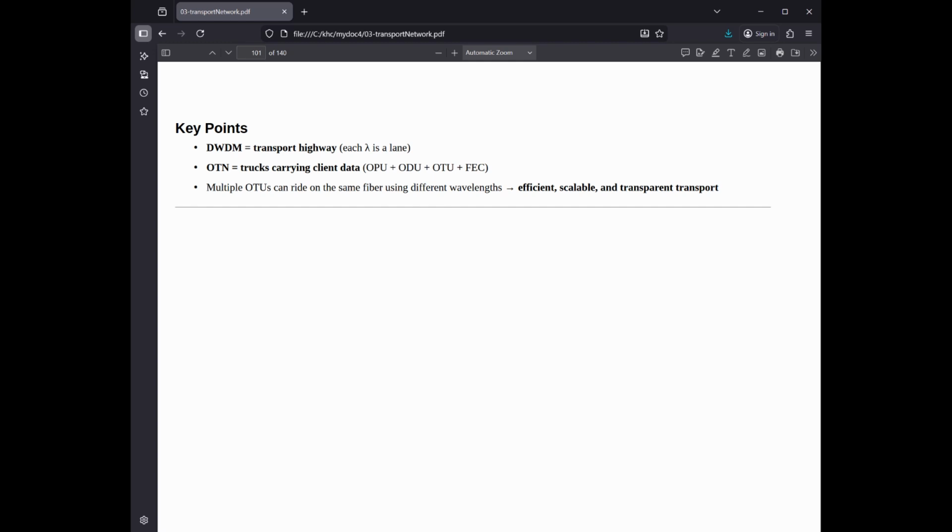Level, unit, key function. Mapping, GMP/OPU: adjusts data rates to fit the OTN frame. Multiplexing, ODUj/ODUk: packs multiple small signals into one big container. OTU: adds FEC and assigns a specific color for transport. Lambda, the fiber.